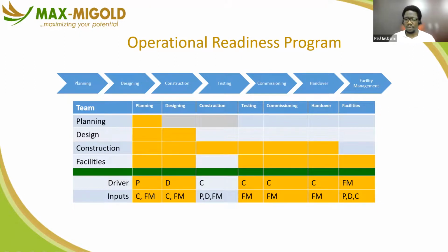It's a quality assurance process to ensure that the formwork is perfect, it is certified, the reinforcement is seen, confirmed, validated, approved, certified before you get the mix. The mix is also checked to be sure that the mix is appropriate, properly mixed and then poured, and then the curing period is counted to be sure that it cures for the number of days it should cure before you take out the formwork and so on. Those things you are doing as the documentation of the processes to ensure the right things are done are called quality assurance activities.